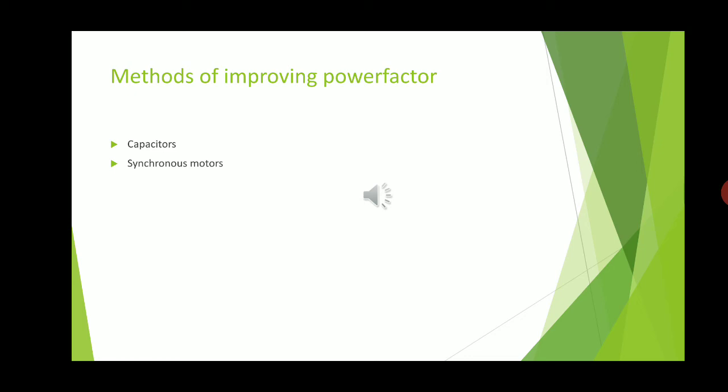Why does it increase the overall power factor of the system? Because the current phasor is always leading the voltage phasor. Now, if you will connect in parallel the capacitors with the load centers, you have seen that the phasor diagram for the inductor is that the current phasor is lagging the voltage. Now if I connect this capacitor in parallel with the inductor, what will happen? It will have the phasor angle exactly opposite to that of what? Exactly opposite to that of inductor.